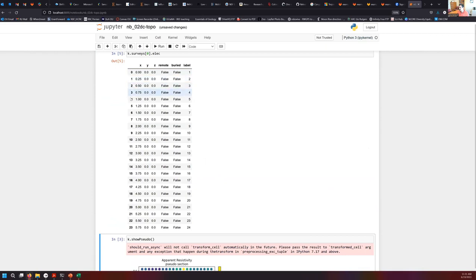Then I'm wondering if they might be referring to the A and B weights. Oh, okay. That is the inversion error weights, and B is the percentage error in your data. A is the offset error. So if you have, let's say, 5% error in your data between normal and reciprocal, you put 0.05 for B.